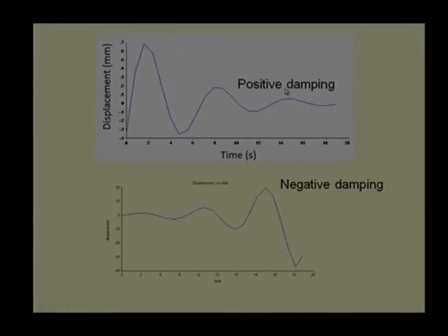So, positive damping with zeta lesser than 1 is an underdamped condition. The displacement goes to a maximum value, comes back to a minimum value on the negative side and the opposite side. Then in the next cycle it goes again to a high value, but lower than the first cycle. We are assuming this is natural damping, not a forced damping system, and it keeps going on, and finally it reaches a stationary condition, and if 0 is the initial condition, it will reach the 0 condition.